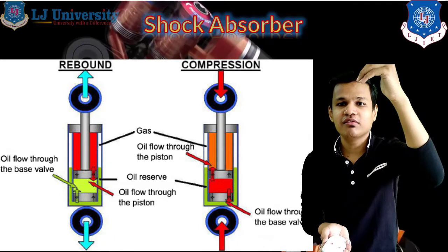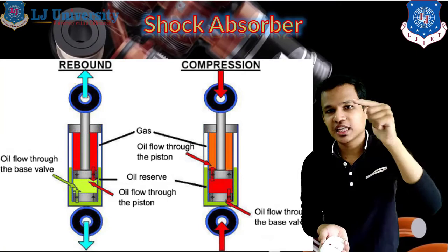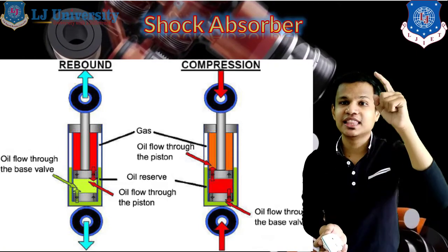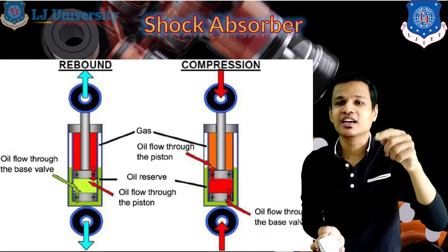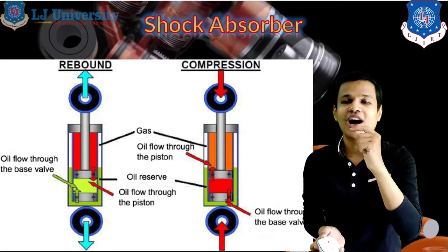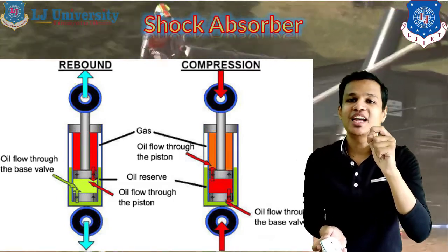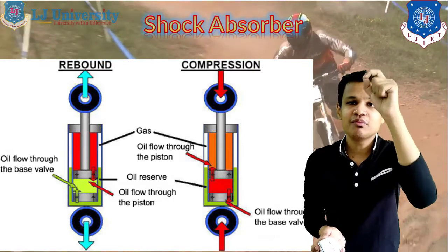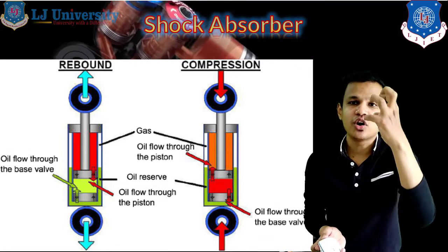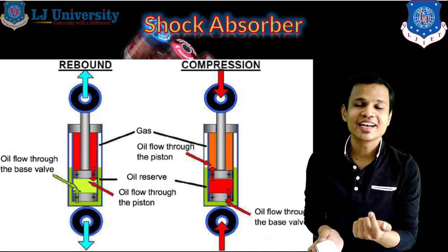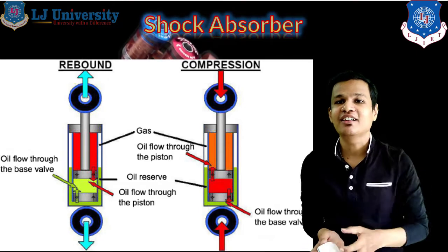Because of that, the oil will come back to its original position, that is between valve A and valve B. Also the oil that went towards the cylinder will come back between valve A and valve B, because from that position the pressure is not required. Valve B is always open from that side, so that from the sideward side the oil can come back between valve A and valve B.